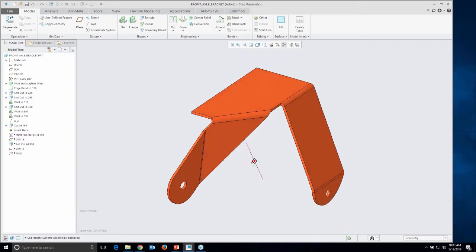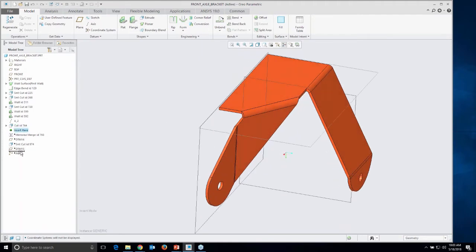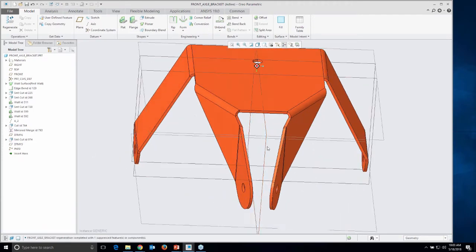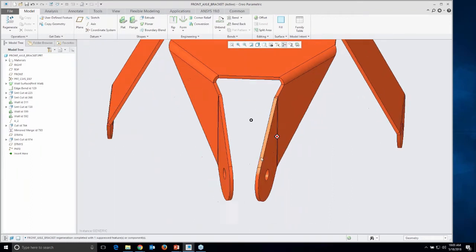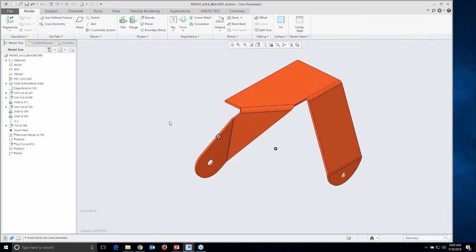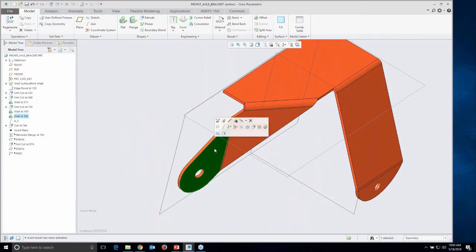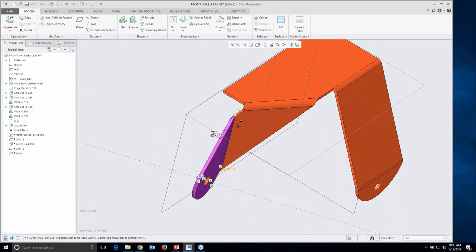So my goal here is this little bracket is going to saddle a little tube. So we want to mirror the geometry like this, and I want these two walls to be flat against the tube. Okay, so what I need to do in that case is I need to make this angle a certain angle so that it will be flat there. I don't know what that number is though. I can't just make it 45 or 90 because there's like another angle there.